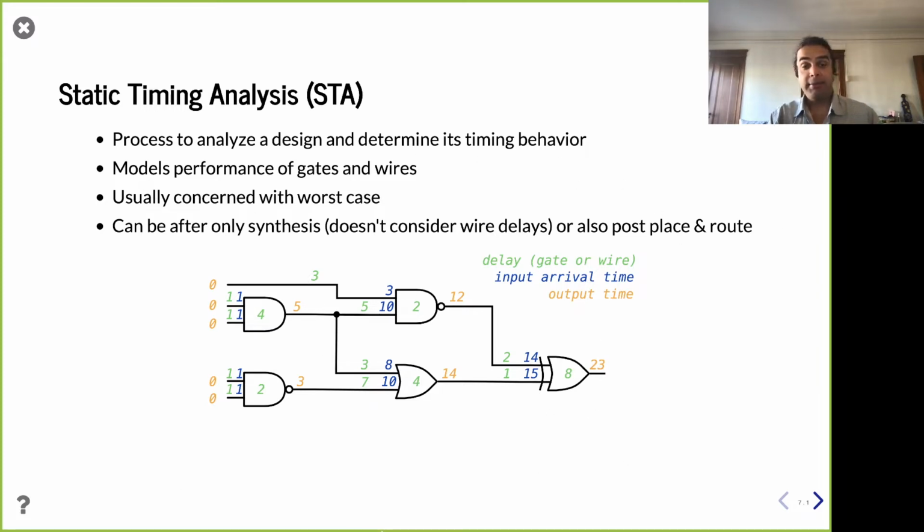And in static timing analysis, they're going to go through and try to find these various paths, right? So, for example, let's say you're worried about your critical path. We mentioned a second ago all possible paths. That's a huge combinatorial explosion. Interestingly, if you're only trying to find the critical path, you can do this in a linear time algorithm, right? So suggested in chat was, this is Dijkstra's. It's not quite Dijkstra, although I'm trying to think in my head if it might be a little bit similar. I can briefly talk about the algorithm right here, but this is not super critical for this course, but this would be where it exists, right?